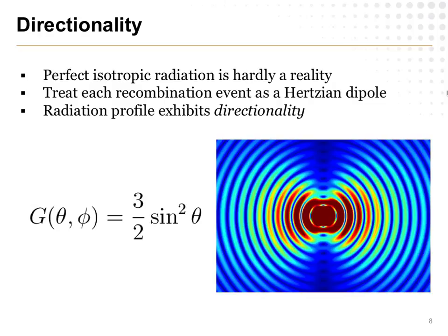I've seen a few people dabble that there is some kind of inherent polarization inside LEDs, but I've never really seen anyone tackle what is the polarization of that electron-hole recombination event. Is it up, down, or is it left, right? Because that actually has a big impact on your light extraction efficiency.